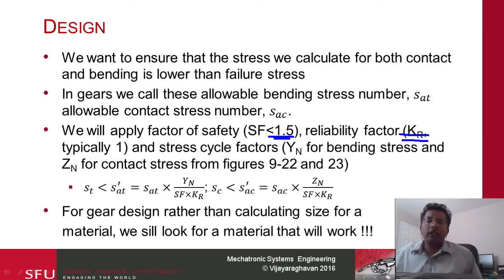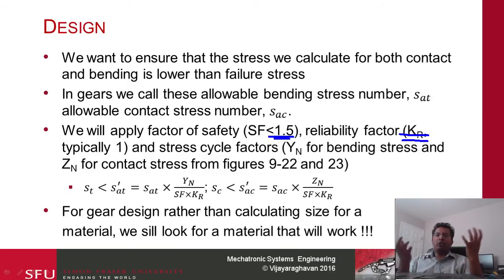So for the previous design, you somehow choose the material, maybe what is cheap or what you think might be acceptable, and then calculate the diameter. If you imagine you're designing a table, you say, okay, I'm going to use mild steel. I know the Young's modulus and the yield strength, and based on that, I'm going to adjust the diameter of the legs and so on.